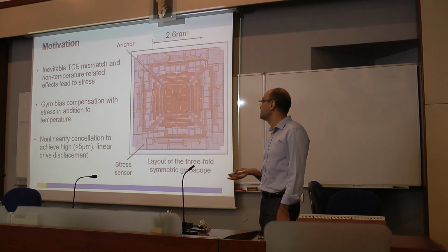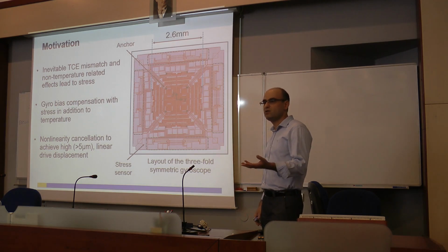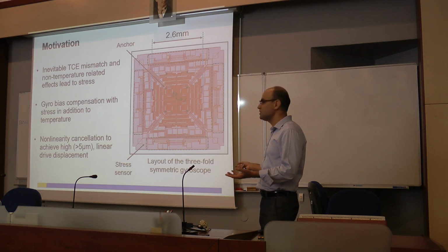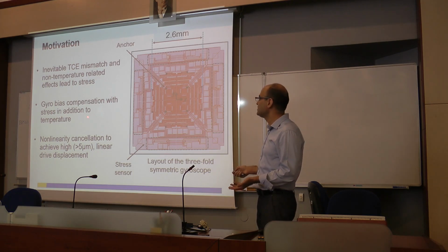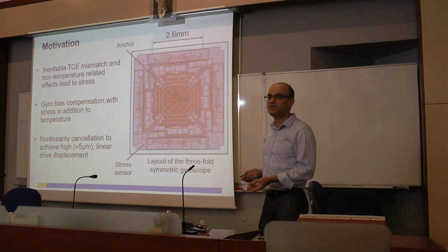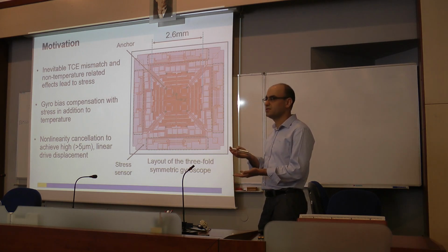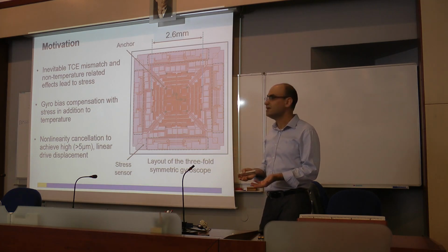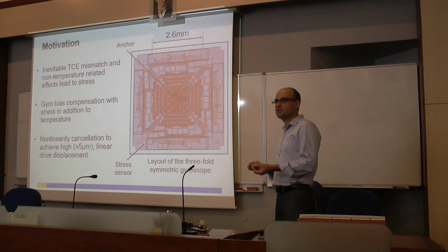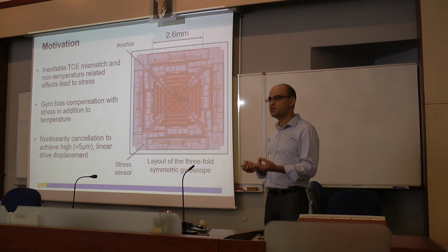interact with its environment. Your gyroscope is made of silicon, and you mount it in a package which is not silicon, so there will be a temperature coefficient of expansion mismatch, called TCE, between your device and its surroundings. Once temperature changes, your anchors and your package want to move differently, and that causes some stress on the device. So this is a temperature-induced stress.